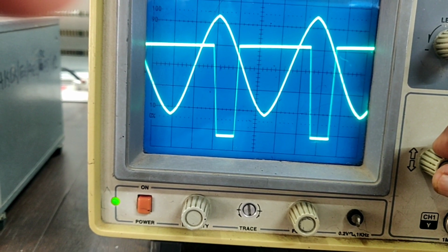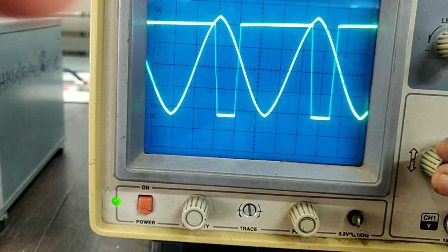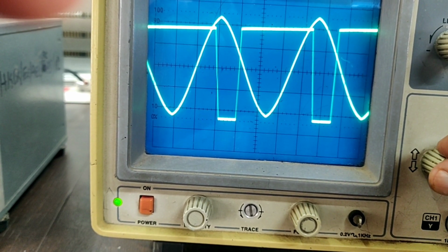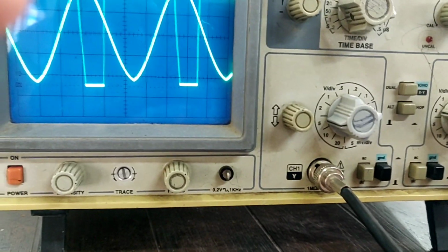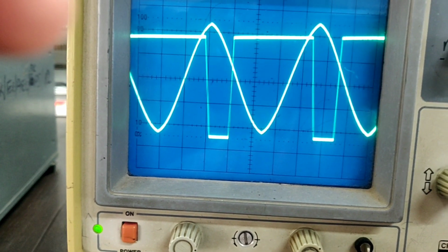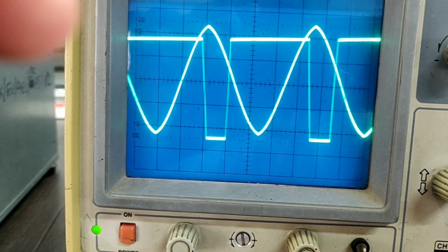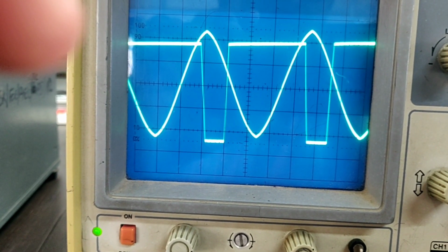Now let us say the UTP. Say it occupies 2 divisions here. So 2 into another, here the volts per division reading is 2 volts. So plus 4. Both the LTP and UTP are on the positive side. That's why LTP is plus 2 volts, UTP is plus 4 volts.